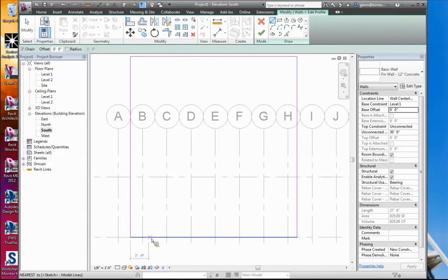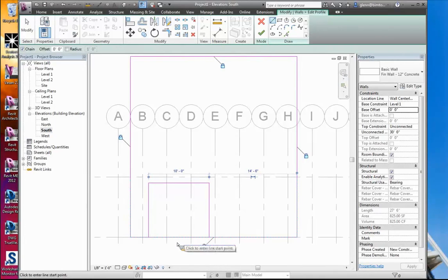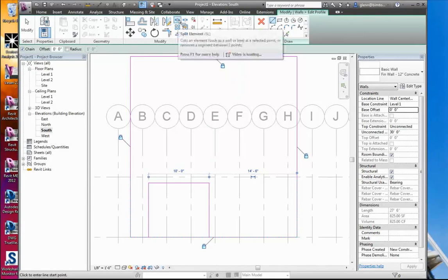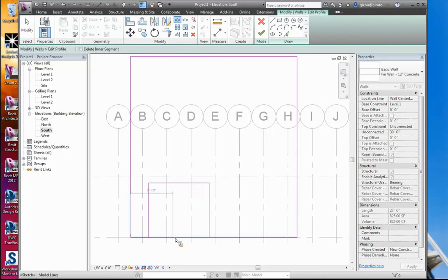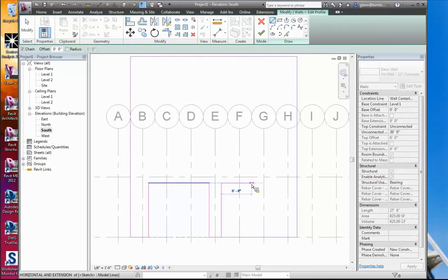What I can do is start just drawing the shape of the openings. Now, that opening right now, you'll notice sort of has an intersection right here and here. So what I'm going to do is split the element, do a little trimming, so I just have a continuous boundary. So kind of the pink line rules apply. Okay, over here, actually if I think about this, then it's got that little door opening over here. Again, I'll do a split and do my trim.